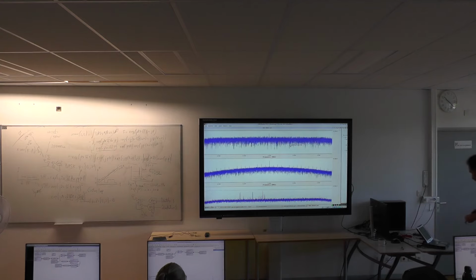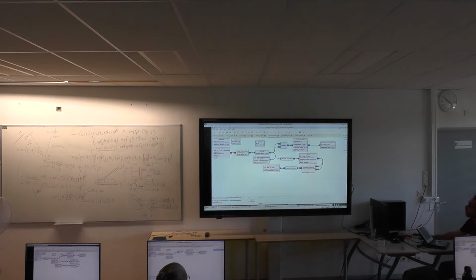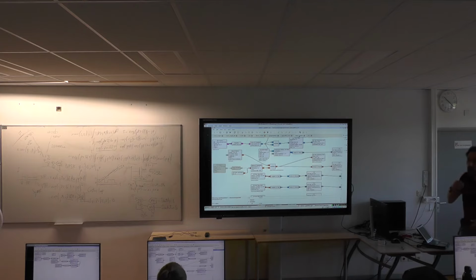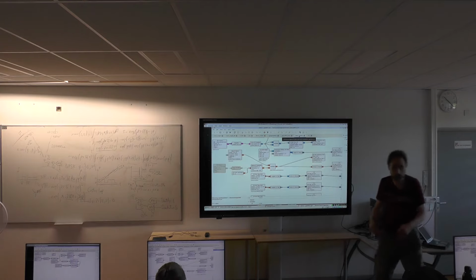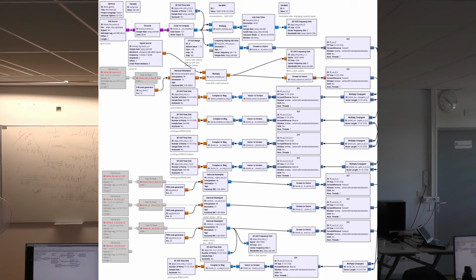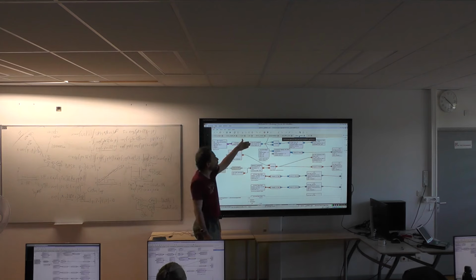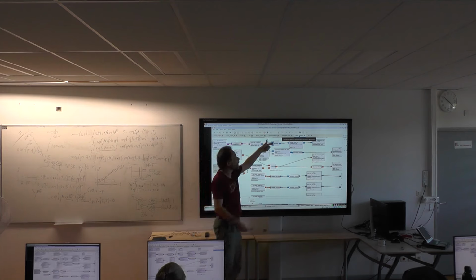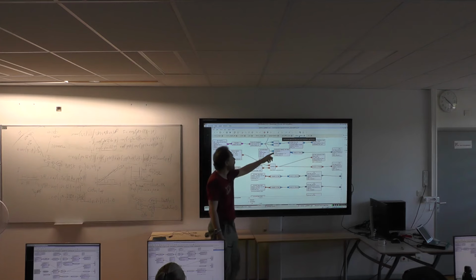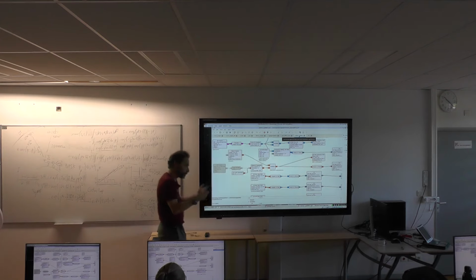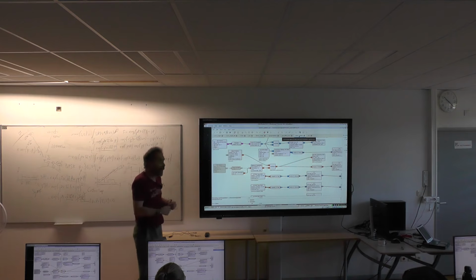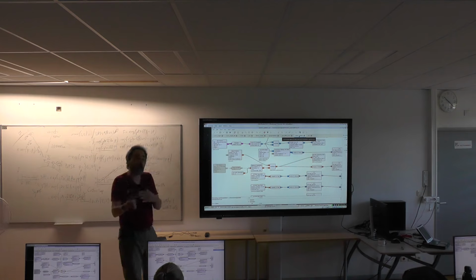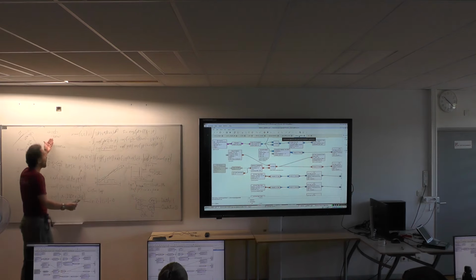Okay? So now is the conclusion of this whole story. I let you go through it in detail at home because there are quite a few blocks. But now that you understood everything, we read the file, we convert from character to complex, we multiply to take the square of the signal just to prove that there are signals. We autocorrelate just to demonstrate that there are signals in there. And then what do we need to do if we want to individually identify each satellite?